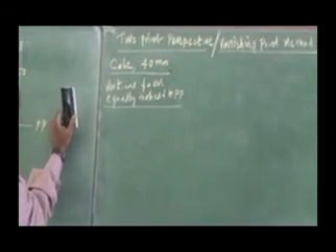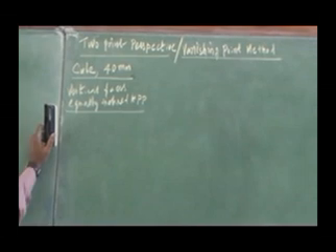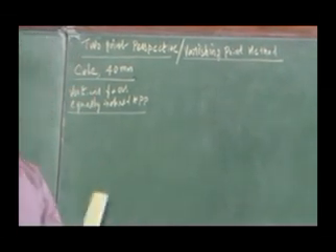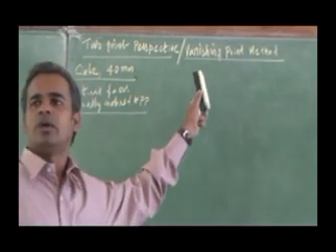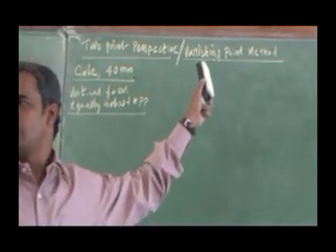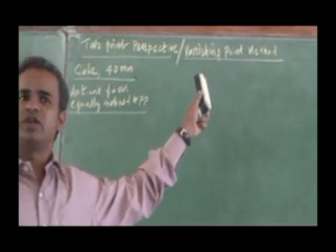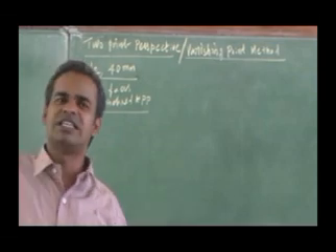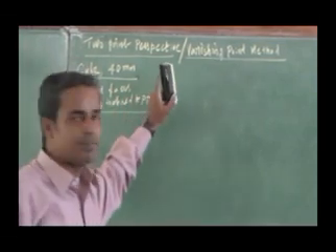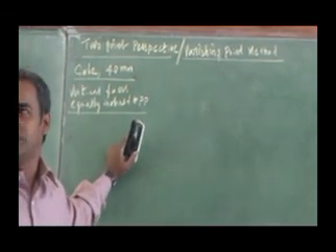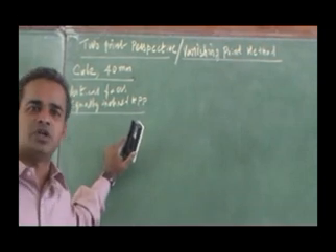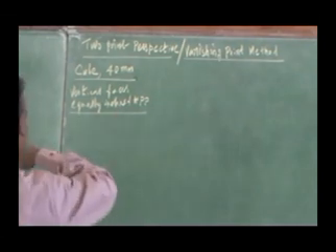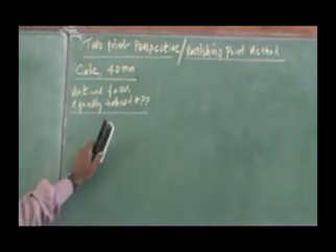But if I go for 2-point perspective, it will be more realistic. That's why if vertical faces are inclined to the picture plane, I can adopt the vanishing point method, that is 2-point perspective. So it is not wrong if you are doing it in a single point perspective. You can do it. The type of method is not mentioned. You are asked to draw the perspective view, so you can adopt any one method. So now, the vertical face is equally inclined to the picture plane.